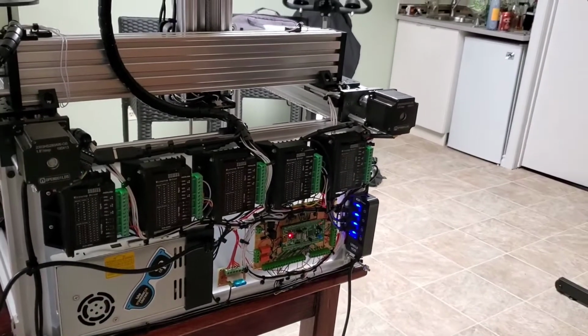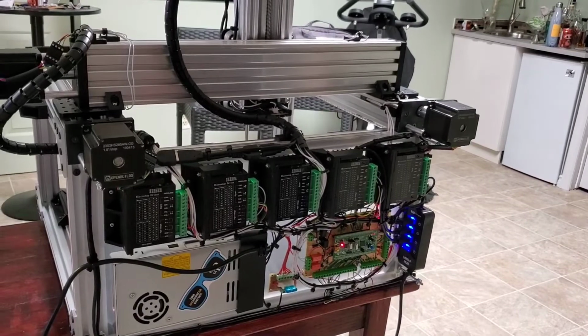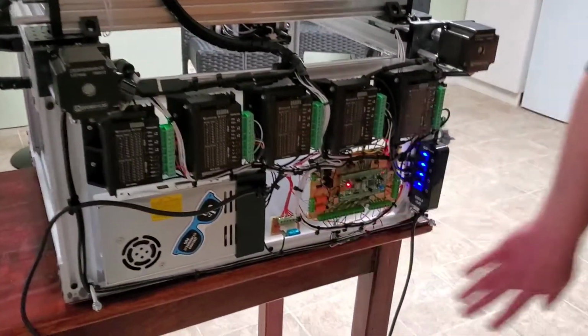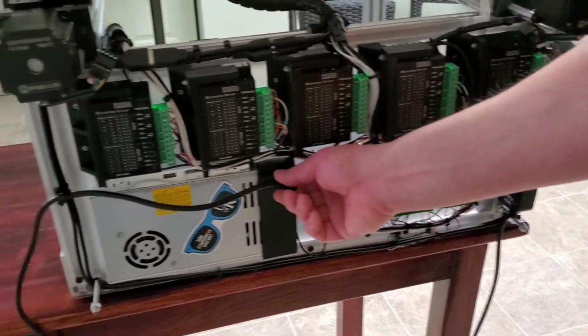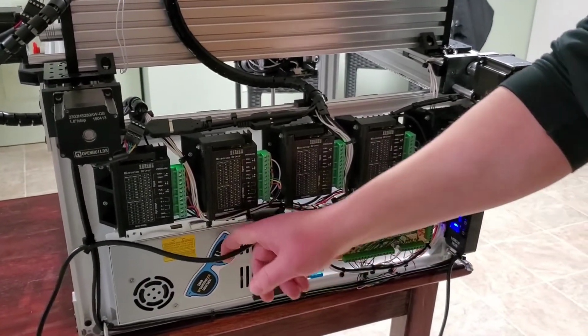Also part of the power supply subsystem would be the wiring and the management scheme that we chose. So we definitely wanted to make sure that we had lots of strain relief so that if anything was to be snagged or tugged incidentally, it would be protected.